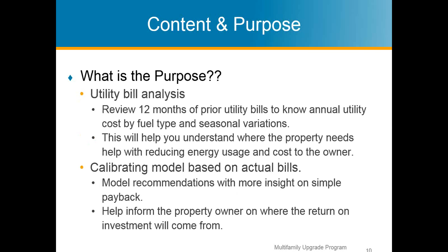Okay, so what is the purpose? Utility bills. So utility bills, you want to review 12 months of prior utility bills before you go out on the site. If possible, you can get this information. It's very, very handy. Even before you get out there, you can review them. You can kind of start trending them just by looking at the utility information and say, when they're using a lot of energy, when they're not.